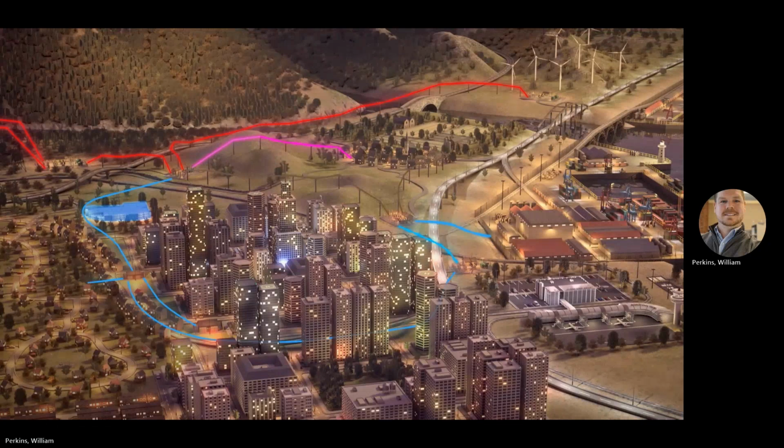The newly repaired line is tested first by closing the primary substation's outgoing switch to substation 2. The line energizes as normal, confirming the repair. The operator can now close the incoming switch to substation 2, reinstating the original supply route.